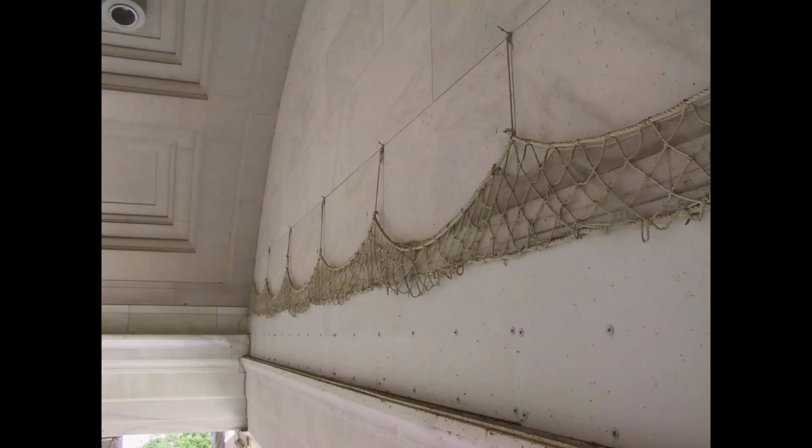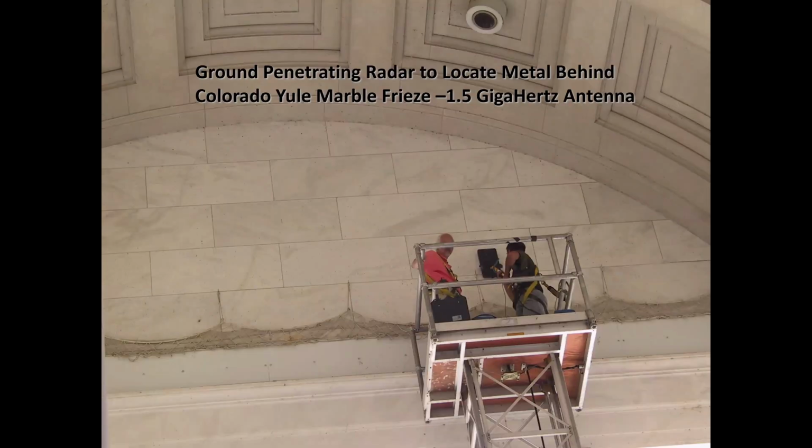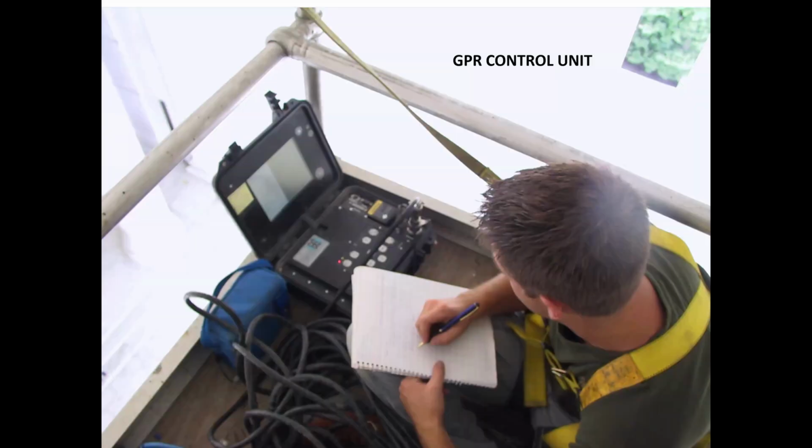There was also corrosion where they had a lintel shelf where the steel was corroding, causing cracking damage. And there you can see the corrosion in that area. So we did some radar to check for embedded metal. And that was a 1.5 gigahertz antenna of an older GSSI system at that time, pushing it up the wall and taking the data into the unit.